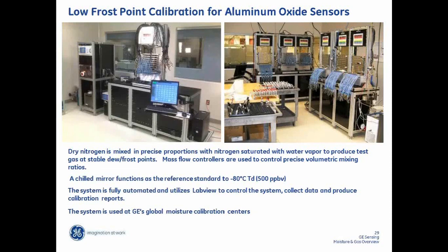Specifically for alcohols like methanol and others, the laser technology works on a bit of a different principle. It's more like a fingerprint, where it's able to discern the water peaks separate from methanol or other alcohols. Now, there are some co-absorbers in laser technology at particularly low levels, and we're going to come up on some techniques of separating out the water signal from some of those co-absorbers as well.